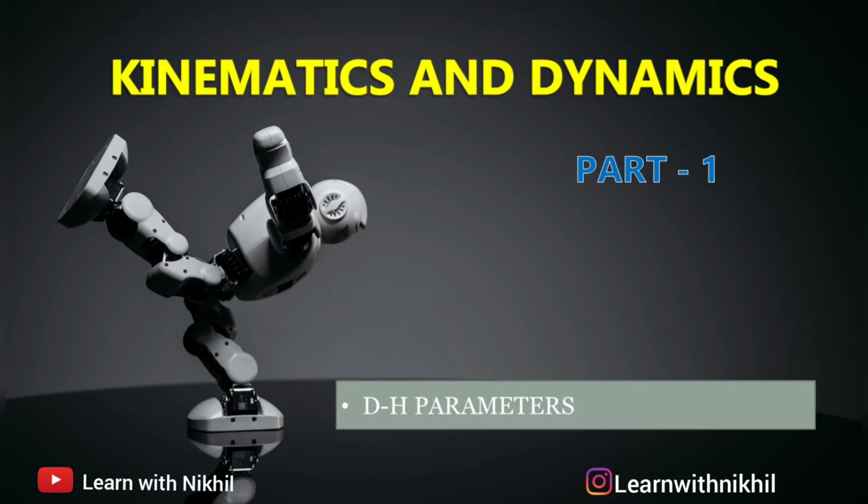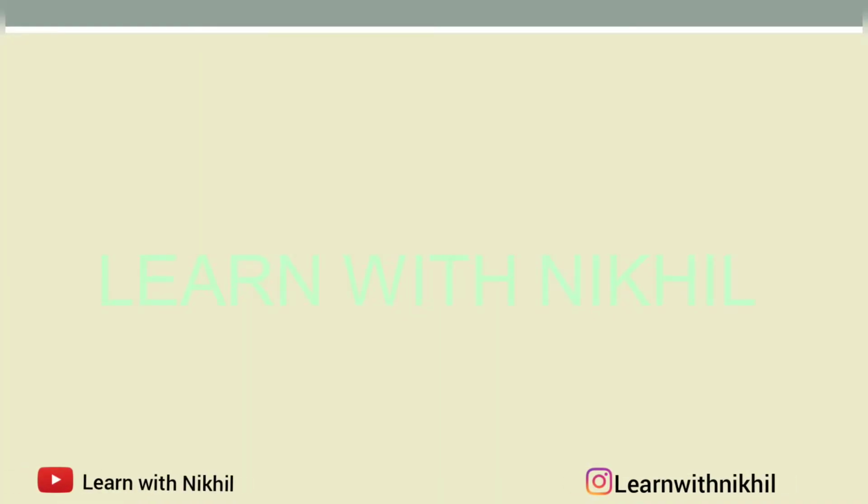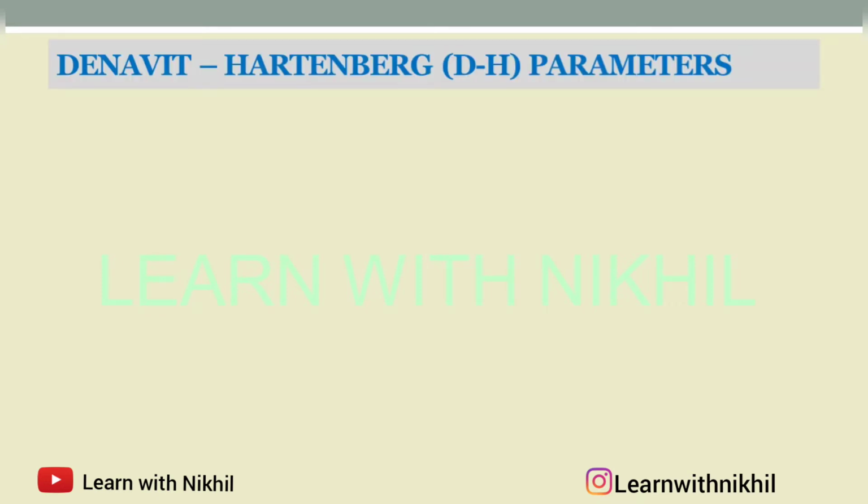So in our previous lecture we have seen how the robot moves in 3D space with respect to the rotation and the orientation. In this lecture we'll see the kinematics and dynamics of the robot using these DH parameters. So let's begin. In our previous lecture we studied that we have 6 degrees of freedom. So to reach a particular point, a robot requires 3 positions and 3 orientations, a total of 6 parameters. But Denavit Hartenberg suggested that only 4 parameters are sufficient to make the robot work.